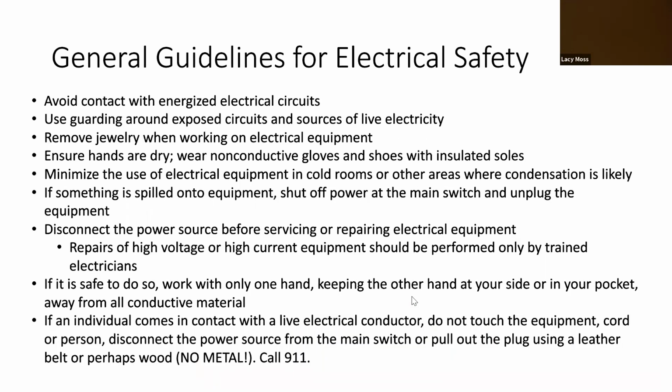All right, here we go. So general guidelines: don't touch electric things. Use guarding around exposed circuits and sources of live electricity. Remove jewelry when working on electrical equipment. I assume they don't mean just your standard plug-in thing, but if you're going to be doing electrical work, I'd take off your jewelry.